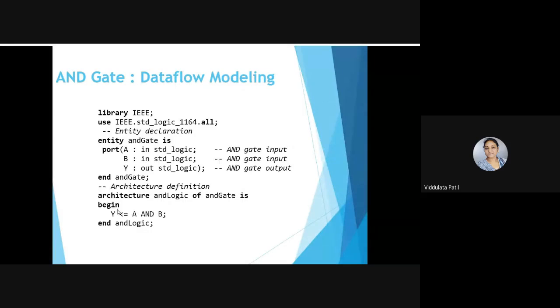If, so here when we are using AND gate, okay, त्याच्यासाठी आपण आता कोड लिहितोय तर त्याचं बुलियन एक्सप्रेशन काय आहे A and B. Okay. So this AND is a keyword or the word that is function that is available in a VHDL program. Okay, so we can directly use that. So here y is assigned to A and B.